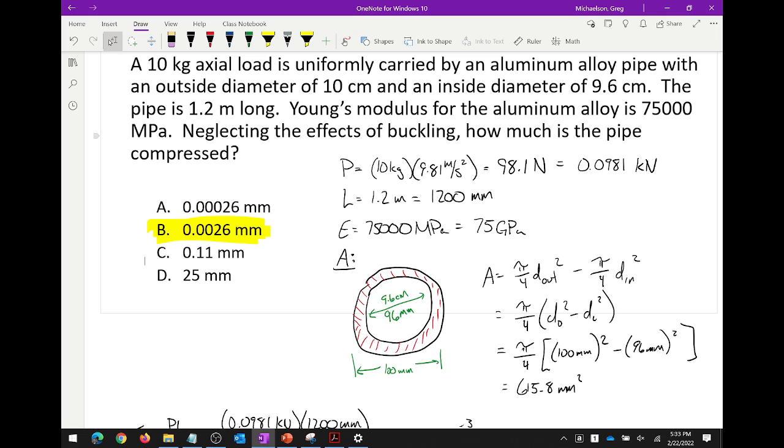Like, it's just a load on a beam. The beam's going to respond the way it's going to respond. The reason for the centroid is because it is the only point that I can determine on any beam. You know what I mean? It is a common frame of reference for all cross sections, right? And it has mechanical relevance because there's zero bending stress and strain at the centroid. So. Sound good?